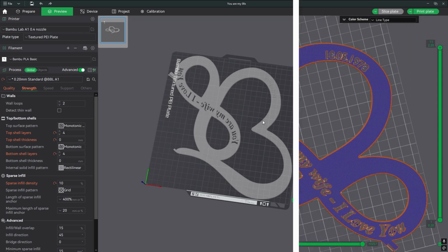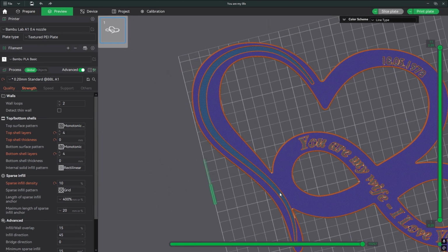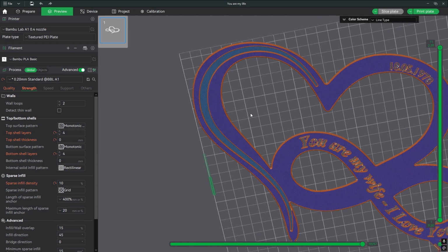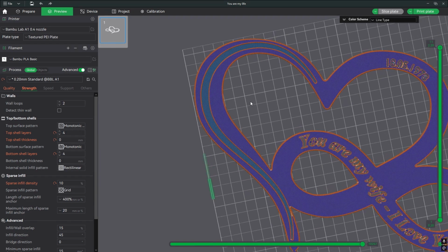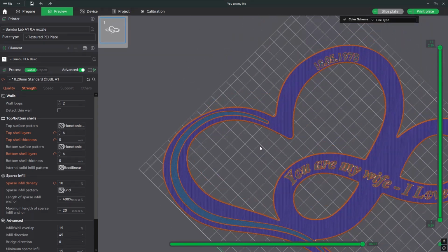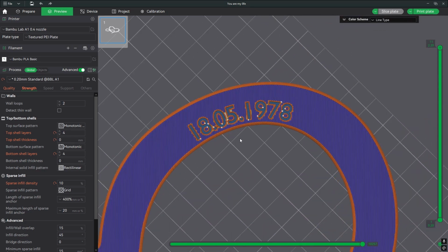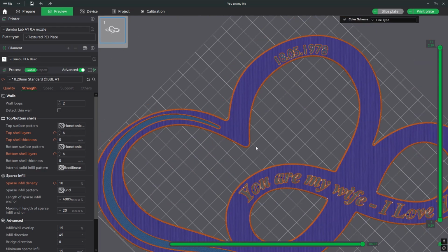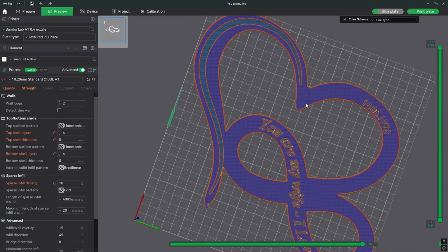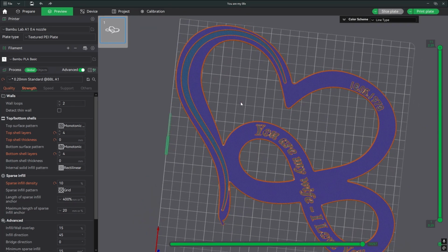and slice plate. Of course, printing these engraved decorations as bridge will result in, I think, a less good looking result. So in this situation in which you have both these engraved decorations and this text up here, you maybe should prefer printing this facing up.